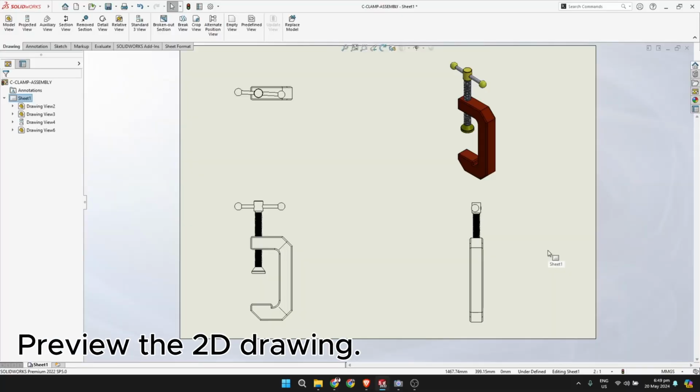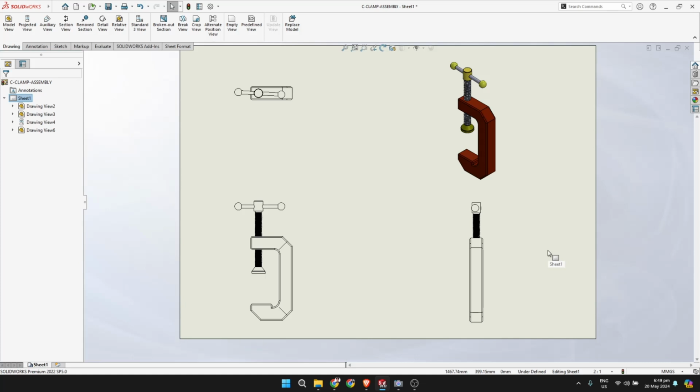Now, let's get started. Before starting the CAD modeling, we need to look at the 2D drawing first. In this way, we can strategize on how we will start our modeling process. We do this to avoid confusion on what we will do first. As we can see in the 2D drawing, there are three views: the top view, the right view, and the front view. In modeling, you need to decide on what plane you should start creating. For me, it is best to start on the top plane.